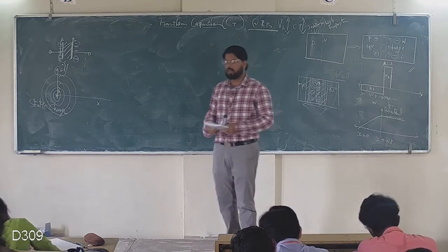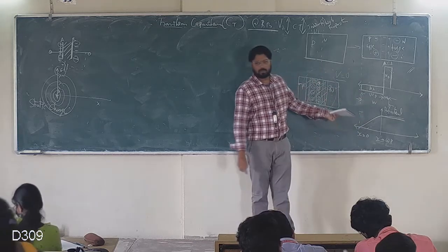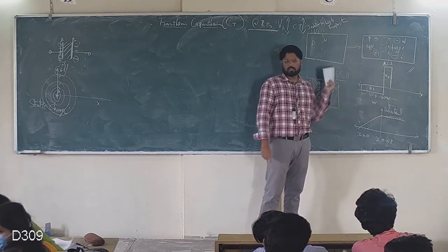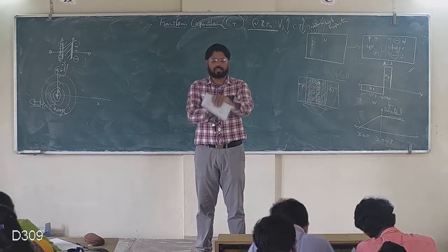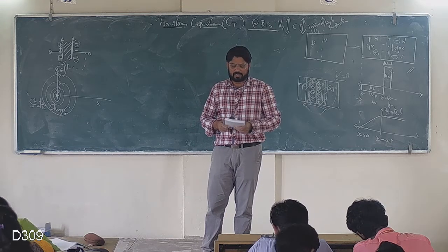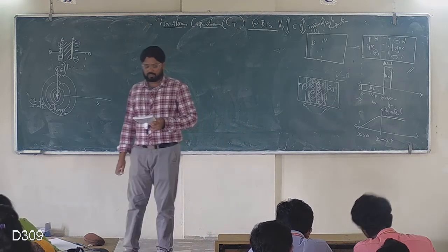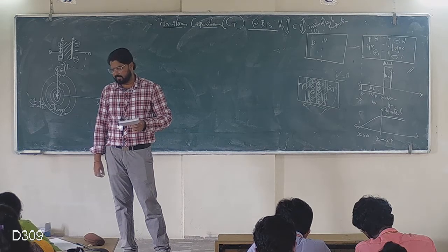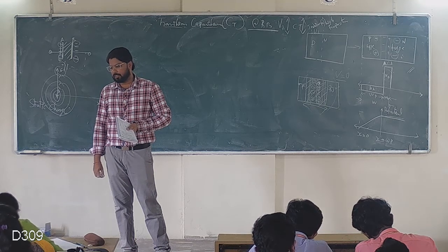Once you draw this diagram, these two diagrams won't be in the book; the book has only this one. Okay? This is just to understand the increase in uncovered charge with applied voltage. Increase in uncovered charge with applied voltage may be considered a capacitive effect.